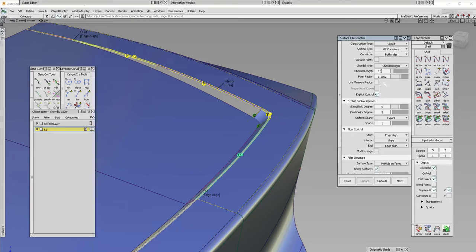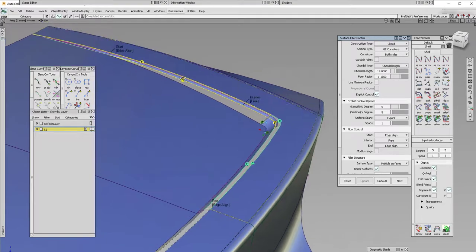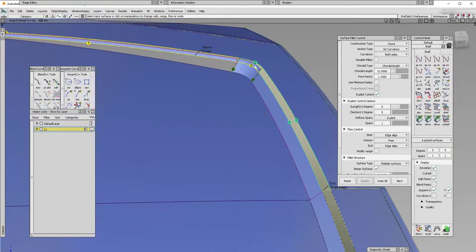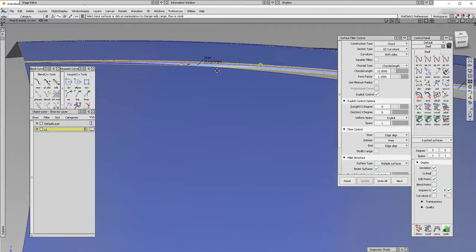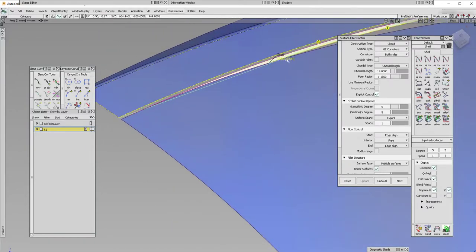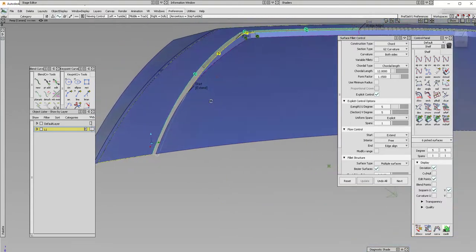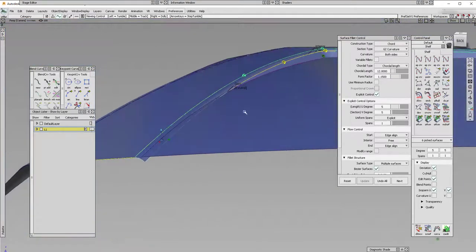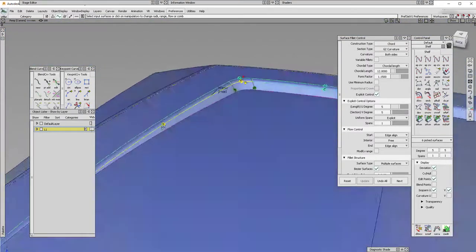So let's make it bigger, 12. Okay, so this fillet will be coming all the way and will be disappearing at this part, and this should not be edge aligned because it creates a weird topology. It should be extend. Okay, we extended this fillet over the boundary, but that's okay. Let's keep it that way.